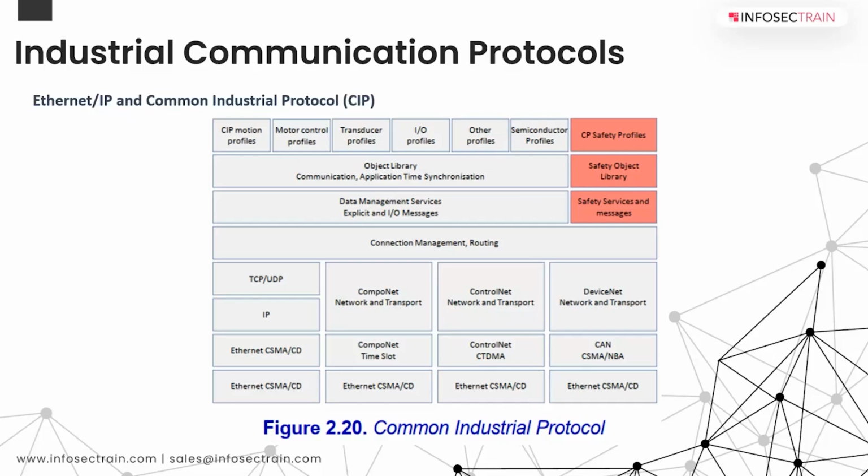So these are some of the challenges, especially when you implement CIP. In addition, the characteristics of some CIP protocol messages, especially real-time multicast, are incompatible with communication encryption. So CIP does not provide the mechanism to do that.